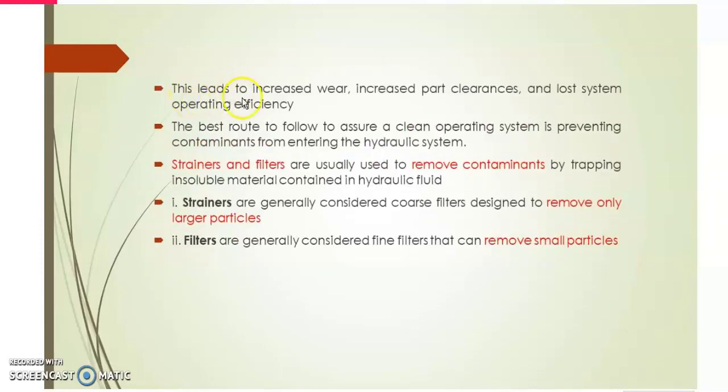So this will lead to increased wear because of the friction due to the lack of lubrication, and also increased part clearance and loss of the system operating efficiency. So the best way to assure a clean operating system is by preventing contaminants from entering the hydraulic system. That's why we need to use strainers and filters. Strainers and filters are usually used to remove contaminants by trapping insoluble material contained in the hydraulic fluid.